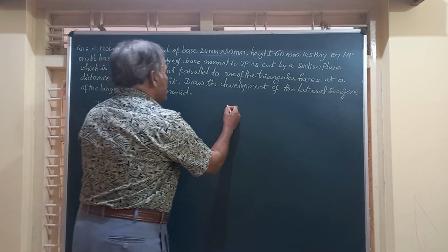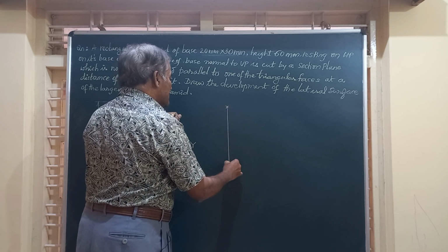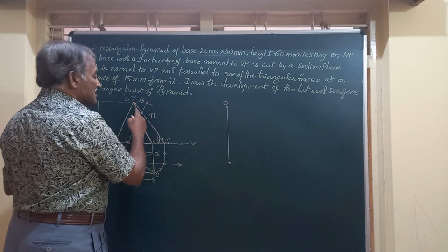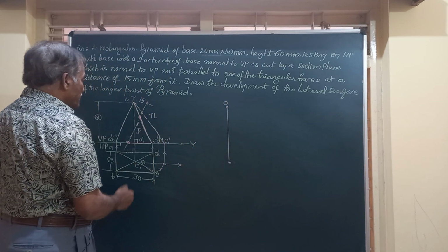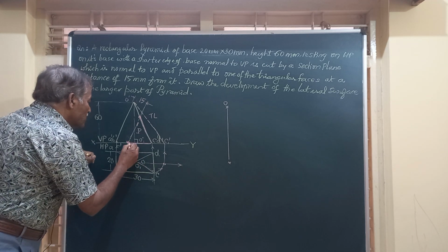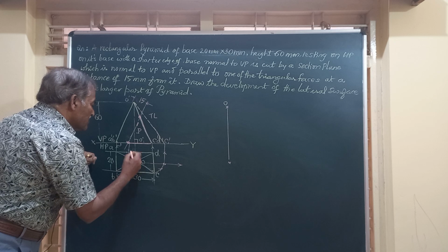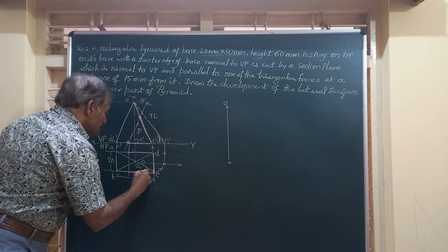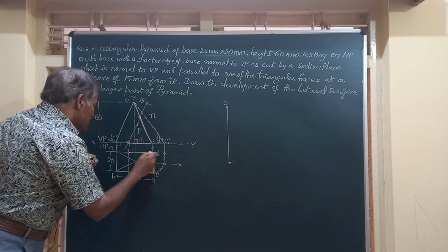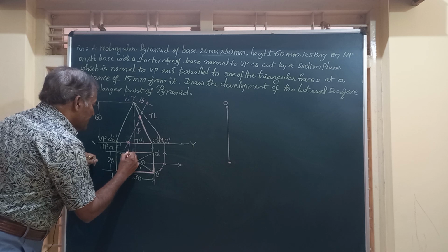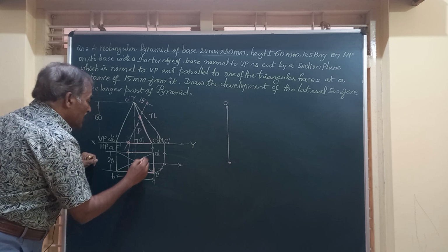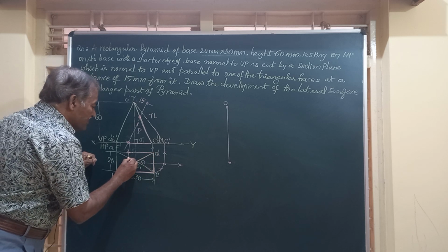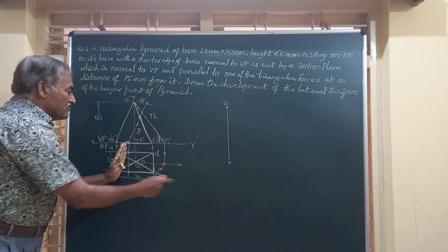Now friends, I am going to mark a vertical line, say through this, and this point is O, the vertex, and here friends, the part that is retained is P. Let me show that in the top view also. So friends, this much portion of this solid is retained. That is, this is for the base edges, 2 points are here, and this for the slant edges. So friends, this much portion of the solid is retained from here onwards.